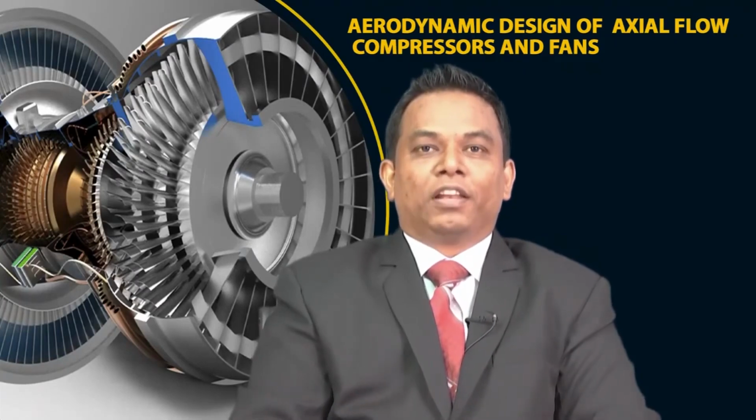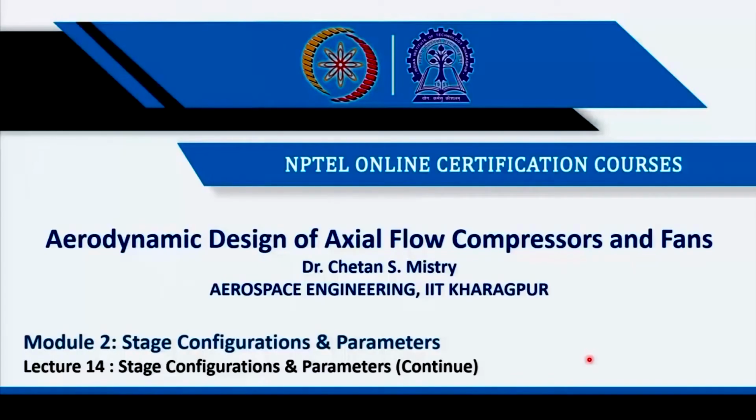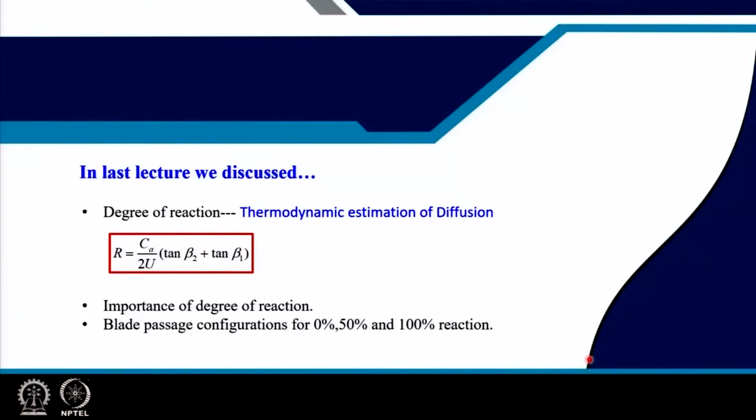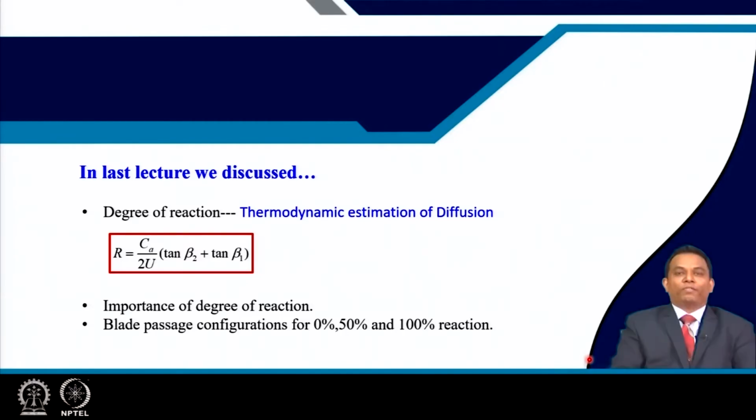Hello and welcome to lecture 14. In the last lecture, we were discussing degree of reaction, which we defined as the static enthalpy rise in the rotor divided by the static enthalpy rise in the stage. This parameter represents our thermodynamic diffusion. So we can define degree of reaction as a thermodynamic estimation of our diffusion.